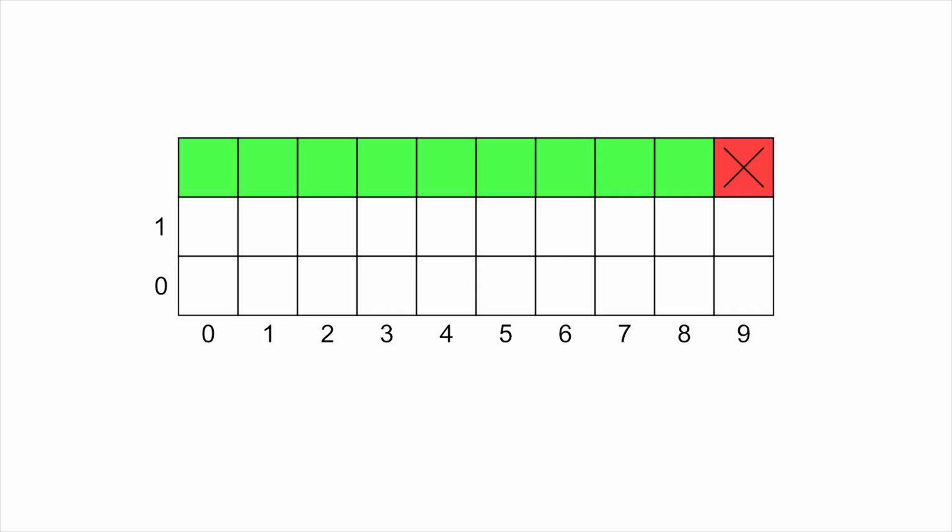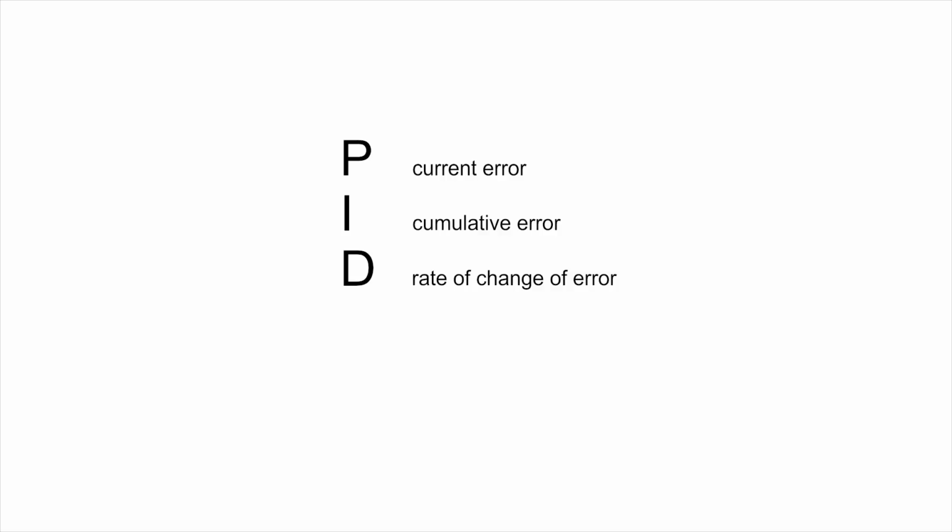We have no other nagging issues, and we can start putting some improvements in place. I wanted to experiment with PID control, and a PID control is pretty simple. It's proportional integral derivative. And what that means is that you adjust your output rate based on 3 things: the current error, the cumulative error, and the rate of change. And then you adjust each one of these contributions to how much you output.